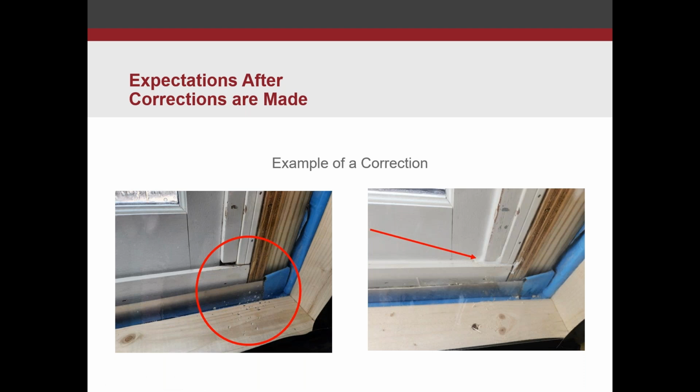So what was the repair? Because the unit was non-operable and would never have to function or open or close, they utilized sealant to seal up that gap and any other slight gaps or openings that may cause the same type of condition. By doing that, that stops air passage. So without the air movement, it doesn't pull water through.